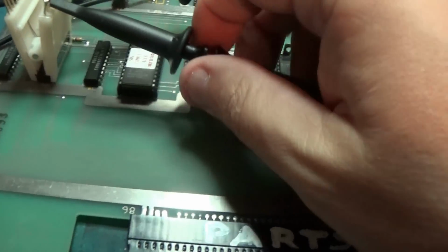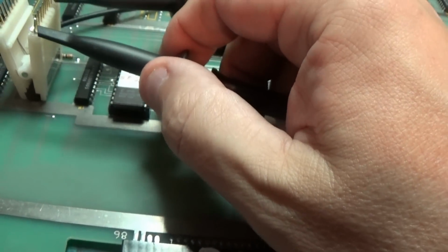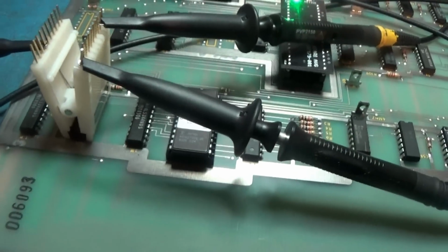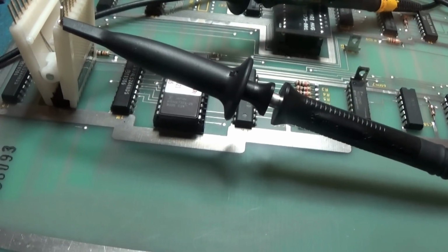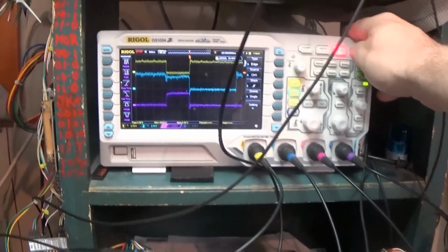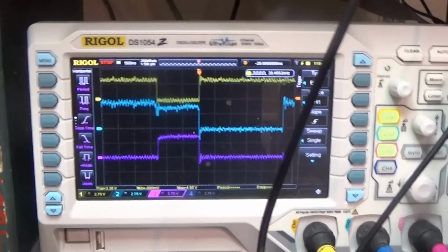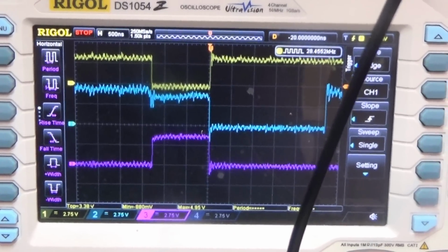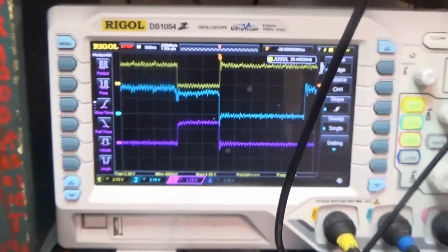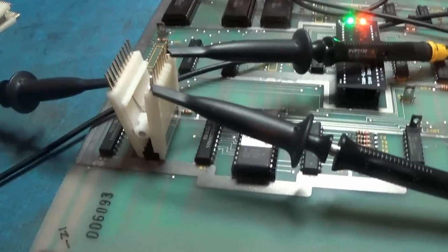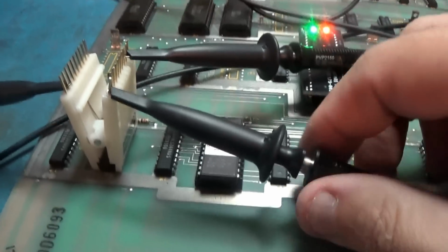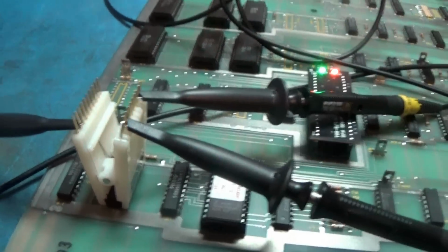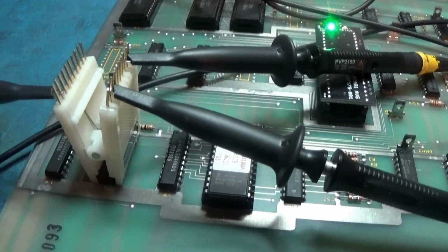Now, every other signal on this driver, let's go to this guy. That's an input, and we'll go to its output right here and get a snap. You'll see this signal goes low and high, as does every other input on here, but that one just does not drive low, and I don't know if it's supposed to be like that.